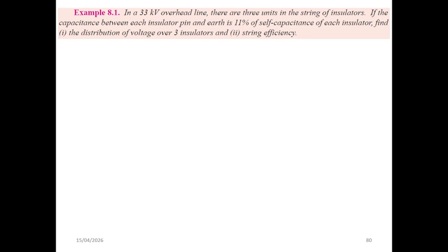highlighting the non-uniform nature of the voltage sharing due to these capacitance effects. In addition, it requires the calculation of string efficiency as an important parameter that indicates how effectively the insulator string utilizes its units under operating conditions. And this example helps in understanding practical voltage distribution and performance evaluation in high voltage or HV insulation systems.